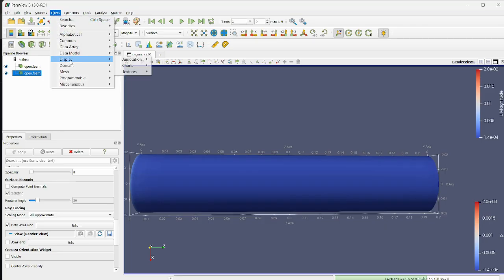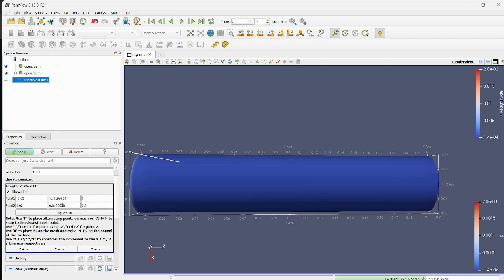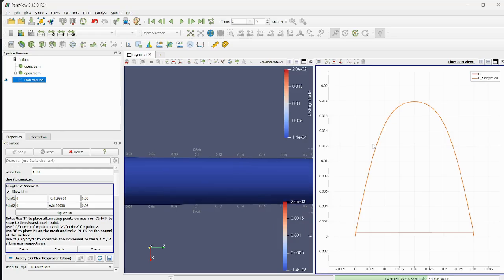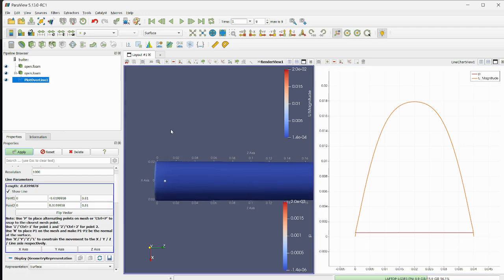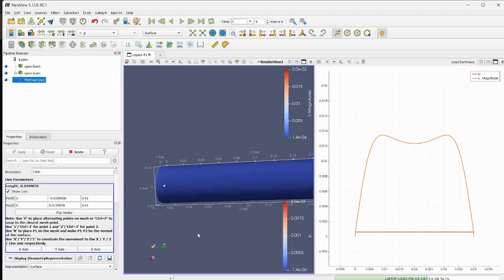So if we were to take a line scan across, we'll do that at 0.03, for example. So this is before the flow is fully developed. You can see this parabola is blunted, which is a pretty clear indication that the flow is still developing. And this is a bit more apparent if I go even earlier on in the pipe. So this is just 1 centimeter in, which would be around here. You can see the line scan doesn't resemble a parabola at all.